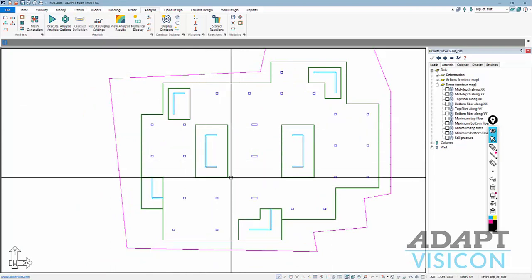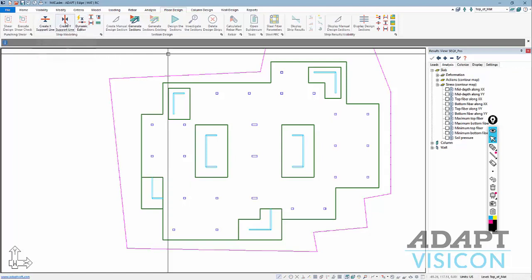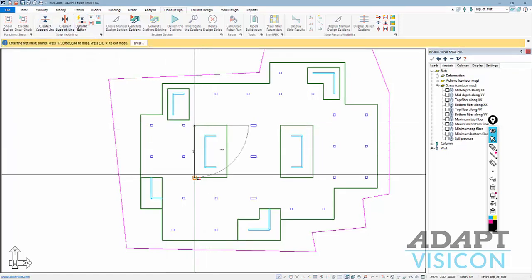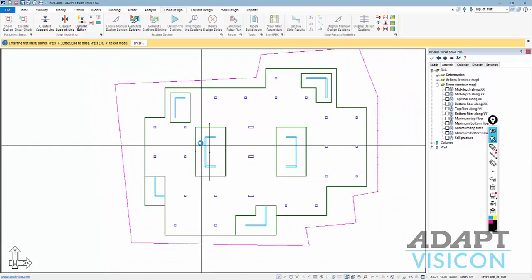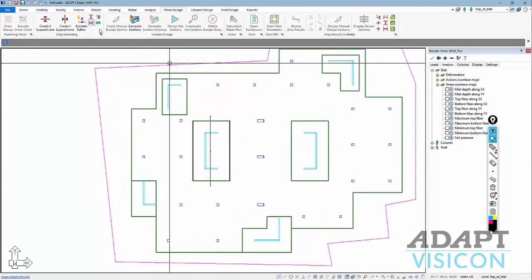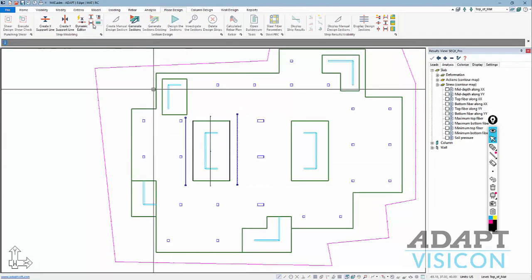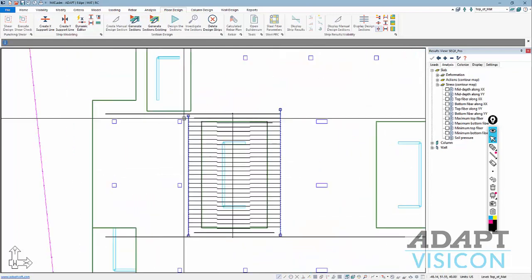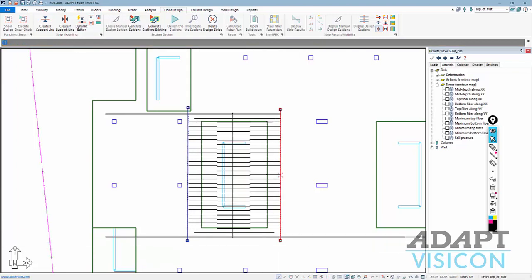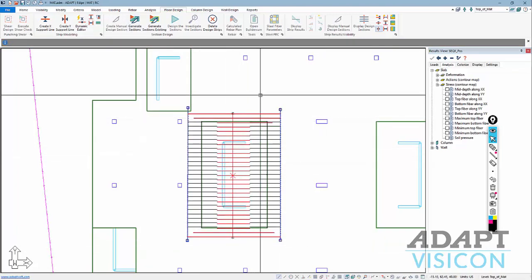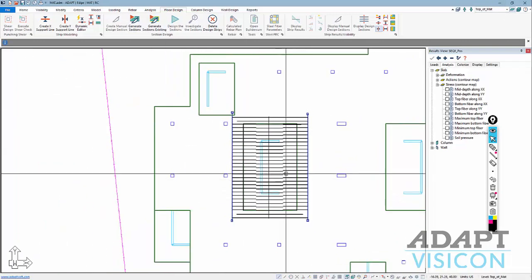So if I want to design this area right here for this mat, I could set up my design strips. I might have a strip along this line, maybe here, and maybe one along the middle there. And in this direction, if I just add a boundary there and there, I'm just isolating the slab into this location. Let me stretch that boundary up. Okay, I have my strips here, and now if I design those sections, these sections have to be designed in